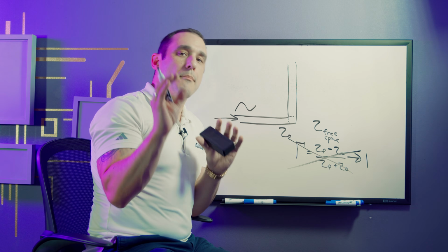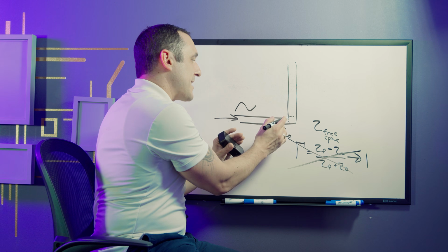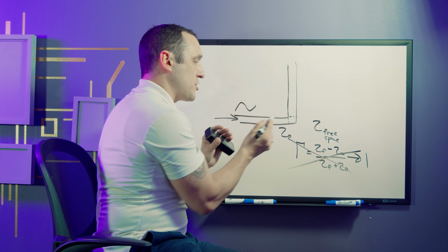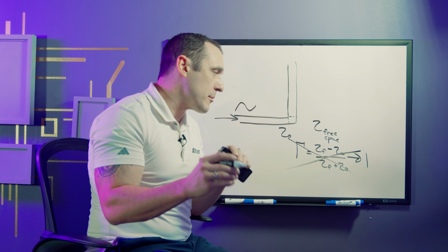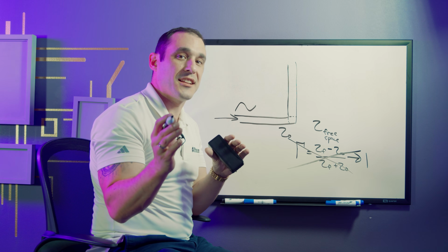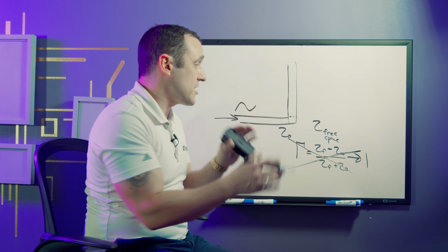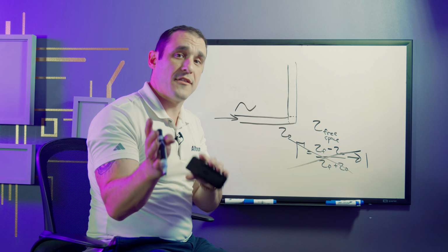But SI Journal is the place to find a series of articles that we've posted there. So clearly there is some minor effect on the capacitance at this location in this right angle bend. And it's really up to you as the design engineer to determine whether or not that additional capacitance will have a major impact on signal propagation in your specific interconnect.